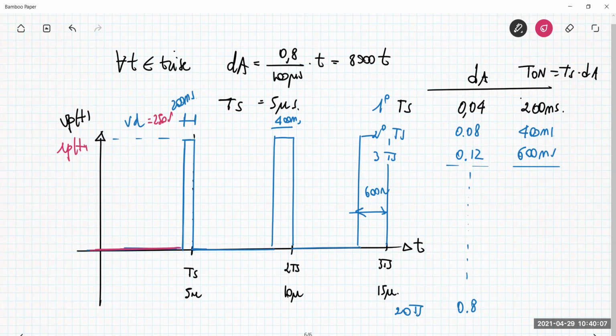We have, say, the node A and the node B. We have a voltage which is 250 volts. We have the inductance, and then we have here the capacitance, Cp. And the capacitance has a voltage across it, which is Vp. What about Vp? We are at the beginning of our T rise. Okay, so it is easy to suppose that the voltage across the capacitor is still 0 in this phase.